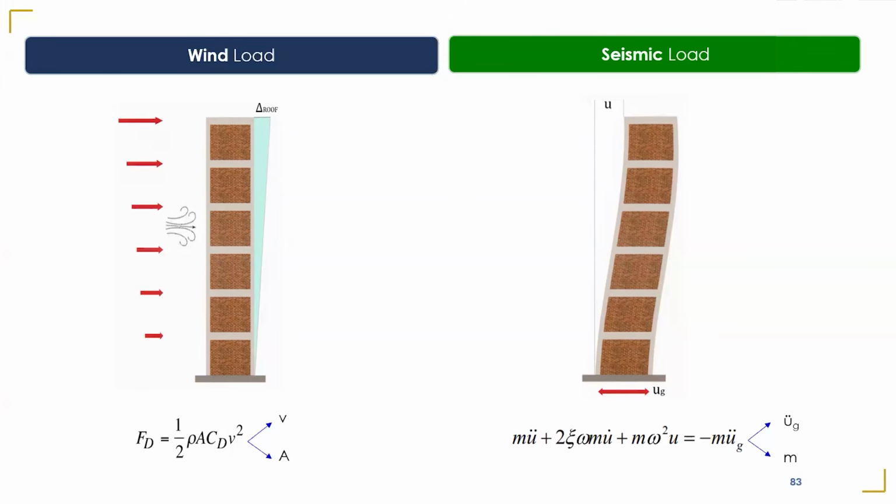So we can design a structure in such a way that it creates no force, base isolation, or we can design a structure which creates a lot of force. So from very large force to zero force, we have the full option to do that. So for the earthquake, the amount of force generated on the structure is going to be our responsibility, somehow in our control.